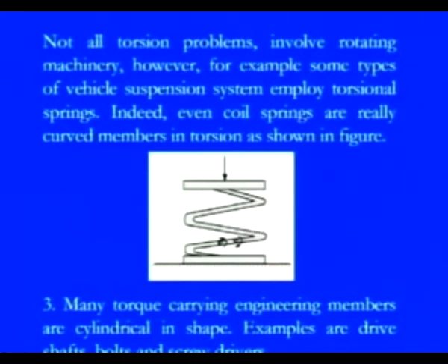because a spring is simply based on stiffness. What you see is the force per unit deformation under the action of shearing. So, we need to consider how stiff the spring is, that means how stiff these spring parts are and how many coils there are. This is a very important figure, and then you see what twisting moment and shearing stresses occur in those kinds of springs.